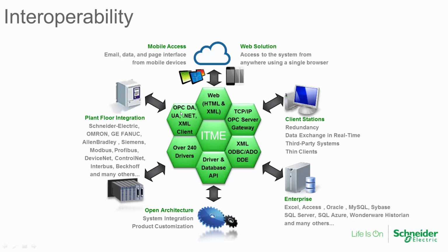We support the OPC Foundation's OPC DA, UA .NET, and XML as clients. And if you need third-party OPC clients to come and get information from our tags, well, we can be an OPC DA server as well. And eventually we plan on supporting an OPC UA server as well, but that'll come in the future, as well as communicate again to any SQL database.